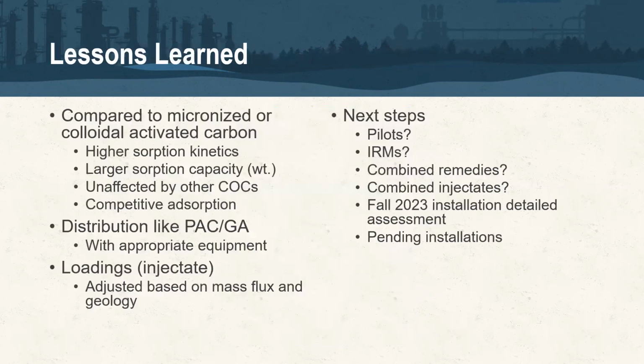So, lessons learned from our pilot here. We did, obviously, in lab, as Matt pointed out, compare the chemical advantages of this Fluoro-Sorb product to activated carbon, which we believe is what most people are comparing it to for in situ applications. We found that the Fluoro-Sorb had higher absorption kinetics, more capacity. As Matt pointed out, it works well in co-contaminant settings and is less affected by competitive absorption.